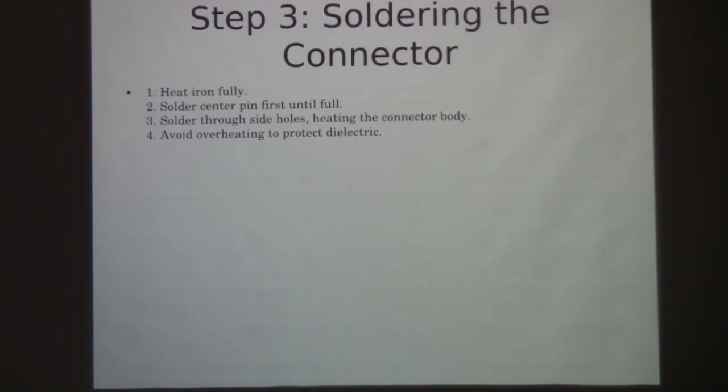Well, yeah, you would put that on first and slide it way down out of the way of where you're heating. One of the problems I've had doing this is using a soldering iron that's really for surface mount stuff. It's not going to cut it. Yeah, you end up melting things. So the idea is to get it hot and get in and out without damaging anything.